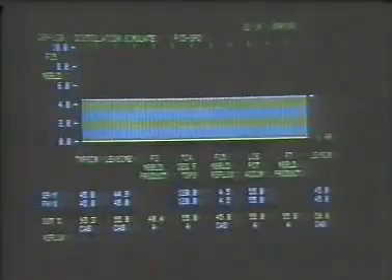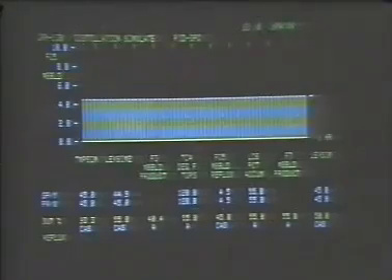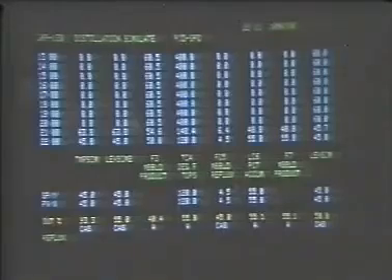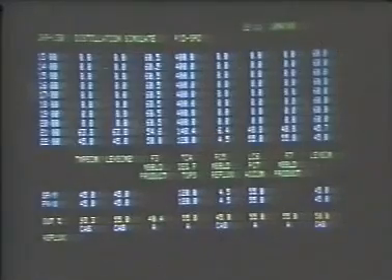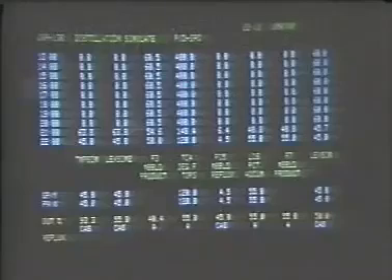No. The operator in this example did not check all the data on the tower operating variables before increasing the reflux rate. This chart shows that the current tower operating conditions have not changed from the previous readings. Had the operator analyzed this data, he might have suspected that the endpoint test was inaccurate because none of the tower operating variables had changed. The most logical thing to do in this situation would be to retest the overhead product before increasing the reflux rate.